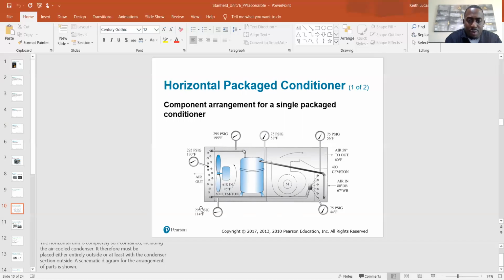And then over here we have our condenser, so this whole entire unit will be on the roof. This is your suction line coming back. I'm sorry, this is your discharge line going into the condenser, not into your evap coil. Do not quote me on that. That was a brain fart. So your discharge goes into your condenser, and then it's going to come out as liquid, feed through these distributors into your evap coil, boil off, and come out through the suction line as a gas and back into your compressor to do the entire thing again.